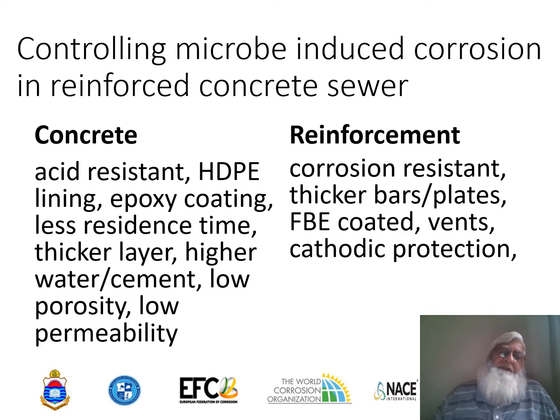So one of the possible ways of preventing this type of corrosion is using a persistent inner layer which can provide resistance to the corrosion, like HDPE, high density polyethylene lining, or epoxy coatings, applied as control measures against corrosion from the microbes.